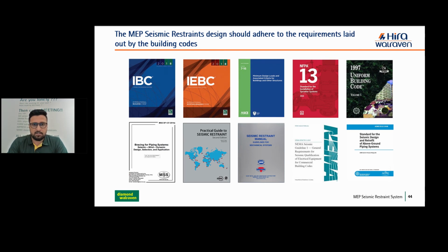While dealing with seismic, we have a few important references, books and standards. In building codes we have IBC and UBC, and when dealing with non-structural components, the ASCE recommendation prevails for all kinds of non-structural recommendations. If we are dealing with firefighting pipes, then obviously NFPA 13 is applicable for all firefighting pipe systems.